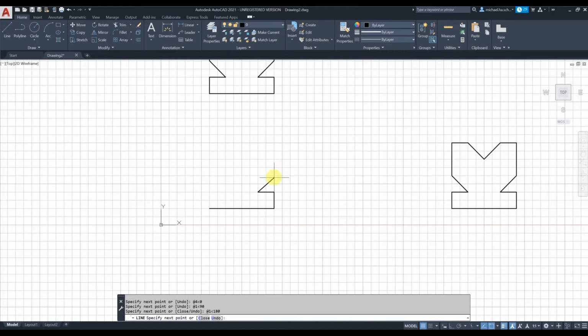For next one, we are not gonna use polar because we are not sure about the length. The length is the square root of 2. That's not gonna be very accurate if I enter it. So I'll be using relative, but in Cartesian coordinates. So add sign 1, 1, right? It's very accurate that way. Then we're going to continue with polar. Add sign 2 is going to be the length and the angle will be 90 degrees. And we're going to speed it up a little bit.